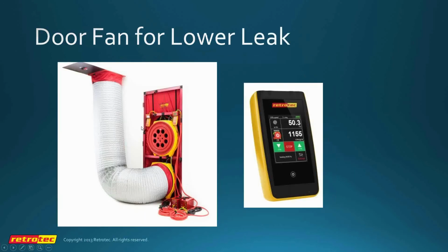The other way to do that is to have a double fan system and to simply duct one of the fans to the above ceiling space here to neutralize the pressure across the suspended ceiling, and then this fan will be measuring the lower leak, which is put into the equations, and this can be done in about 20 minutes or so. The new gauges that we have a set to zero function, which allows the whole process to be automated, and is by far the fastest and quickest way to do a lower leak test and to get sufficient hold time